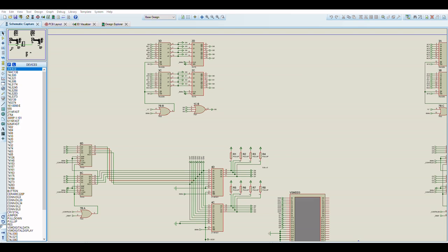However, all of the 384 horizontal pixel positions are used for calculating sprite data into the 256 pixels of the sprite scanline RAM. That's because, if you work it out, 24 times 16 is 384. That gives us our maximum fill rate, if you like.